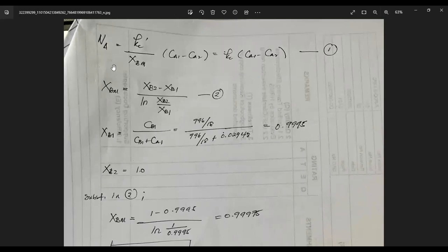Now, I mentioned in the first part of the solution that you need the convective mass transfer coefficient, K sub C prime, in the determination of the flux together with X sub BM. Now, in class, oftentimes, X sub BM does not deviate from 1.0. But I think I placed it in the problem, the modified version that you have in class, that you are not to assume this to be 1. But if you did not assume it and computed for it, actually the answer is very near 1 as well.